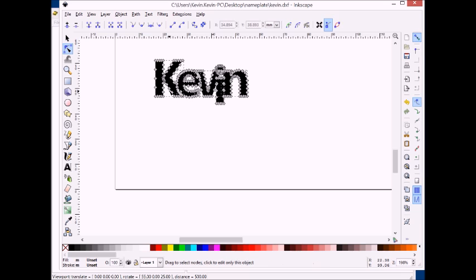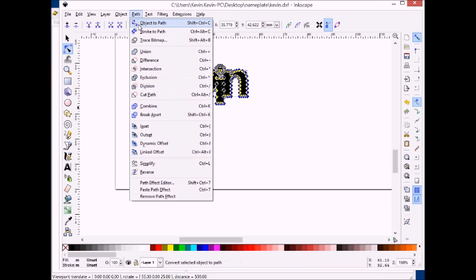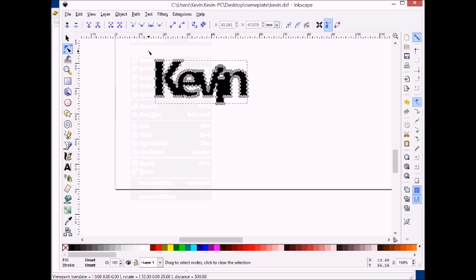And if you export this right now into OpenSCAD, you'll have pieces missing because it doesn't quite know the right order to interpret the polygons. So what we're going to do is select all those points again, and then do a path union, which is basically going to take all the paths and eliminate any points that are inside other areas. So it makes a nice simple path. So now we have a nice path for exporting.